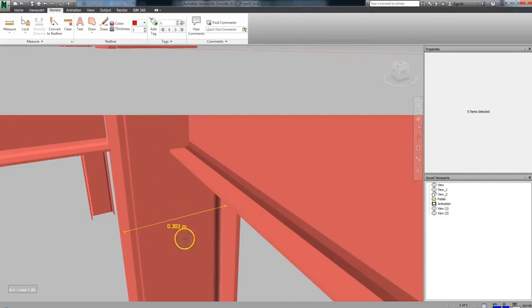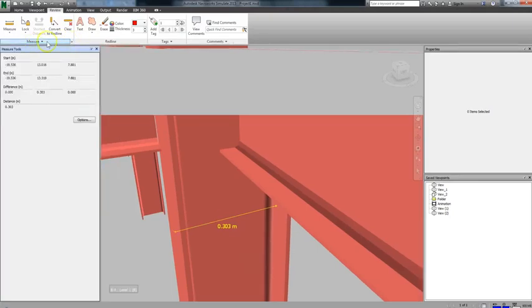If you want to get more information on the measurements, you can always go up to the Measure panel in the Review tab, and left click on the little arrow in the lower right hand corner. So once you hit the button, you can see that it includes the start and end point of the measurement line that you drew, including all 3 axes, as well as the simple measurement itself, which you can also see on the main screen.